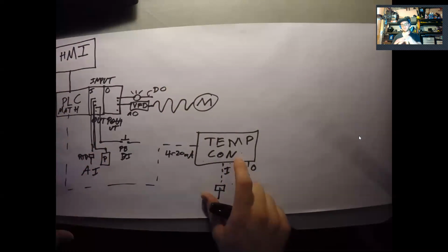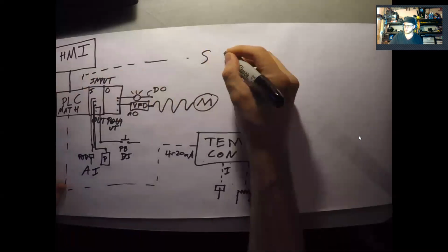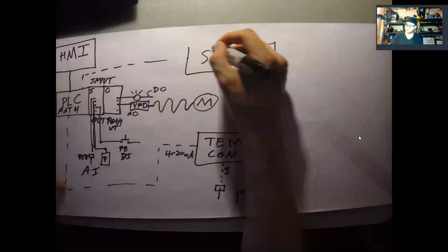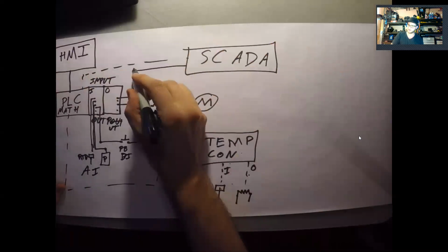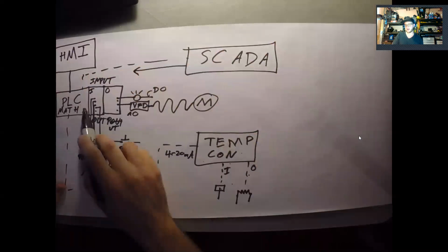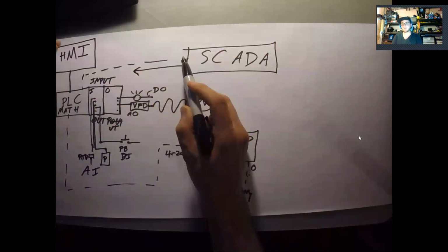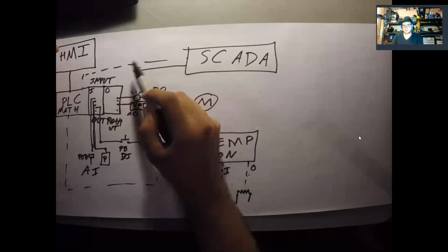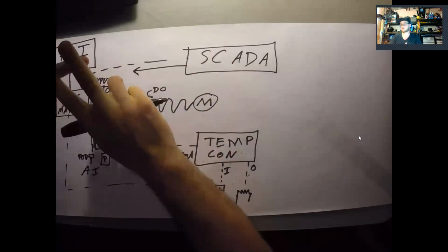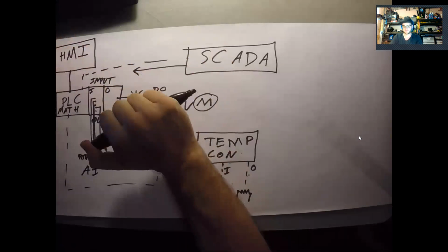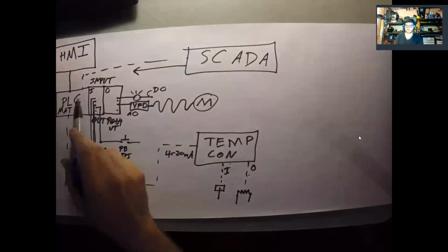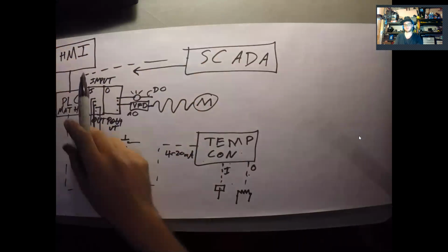And so you'll have another connection to, for example, your SCADA system. And again, you might be pushing down operating set points from your SCADA system, right? And you're also almost for sure communicating up your key operating parameters, which could be temperature, pressure, flow rate, whatever. Or maybe you're just reporting your local set points that somebody came and entered into this controller from the HMI.